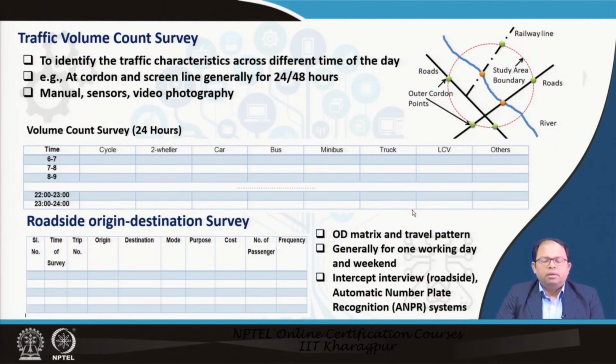Then for traffic volume count, as you can see, for a particular study area, we can have cordon points and screen lines. For example, there is a river, so this could be a screen line, or it could be a railway line, so we can measure the traffic at these particular locations. Usually a traffic volume count survey could be done for only the peak hour, or it could be done across the entire day, for a period of 24 hours or 48 hours to understand the variability of the data, and at different screen lines. It could be done manually or using sensors or using video photography, whichever way is convenient for that particular area.